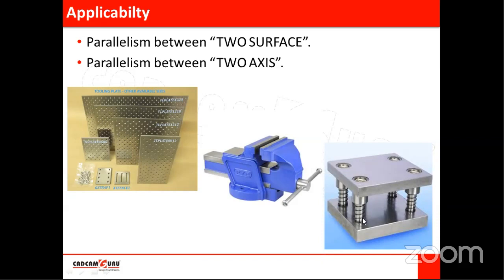So when this upper plate comes down for the punching action, these guide pillars get inserted inside the bushes. Before the punch comes in contact with the workpiece, the guide pillars get aligned with the bushes, ensuring perfect alignment of punch and die. So, due to these guide pillars, alignment of punch and die will be ensured.